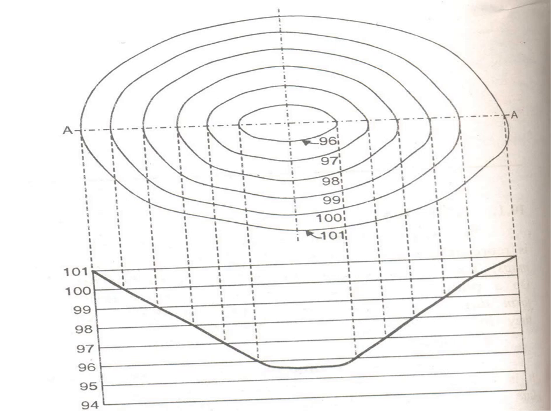Similarly, we can find out the area covered by 97, 98, 99, 100 and 101. And when the areas A1, A2, A3, A4 are calculated, by making use of the trapezoidal formula or prismoidal formula, it is possible to calculate how much volume you can store. That is called capacity computing.